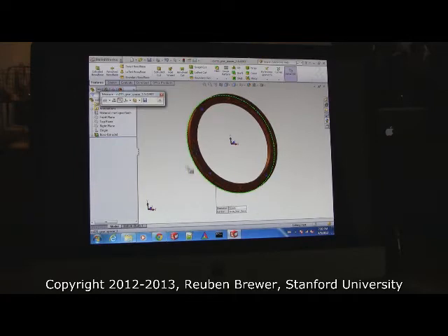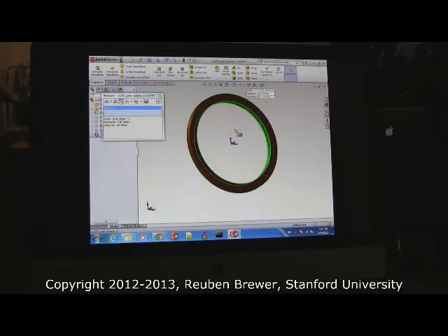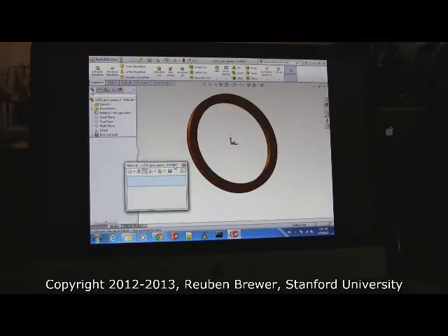So, have I selected anything here? Anybody on my screen? I have, but I don't see a number. Sometimes it hides this right here. Click that little tab. So my diameter is 98. Cool, that's what I wanted it to be. Let's test the diameter of this inner surface. Diameter 82.5, sweet. Now click the origin and click one of your holes and see what that radius is.